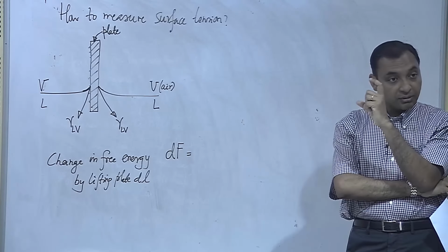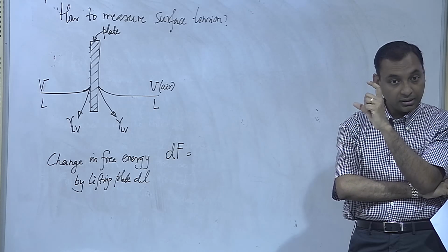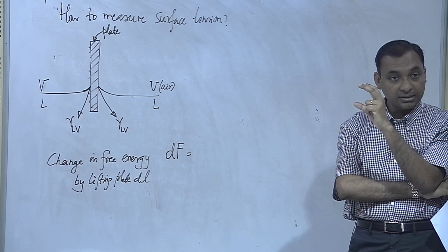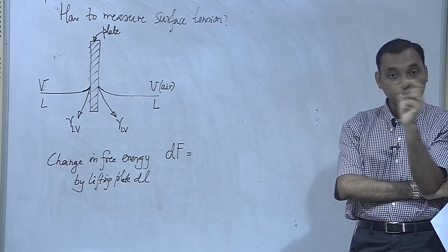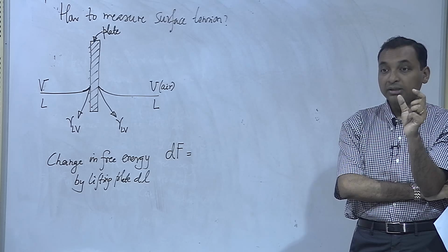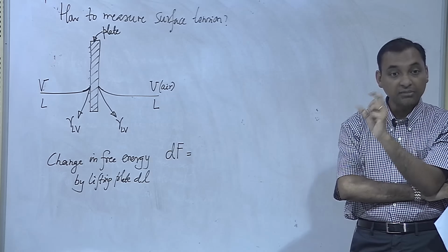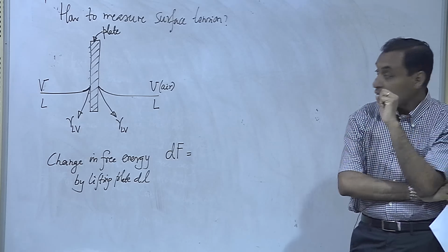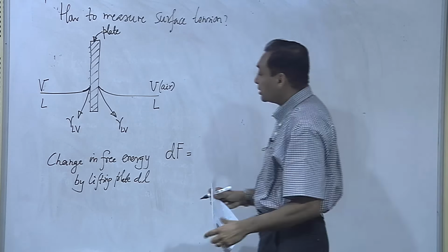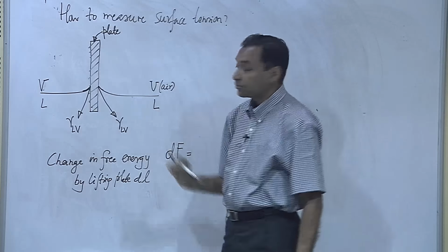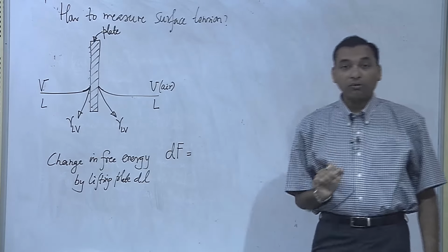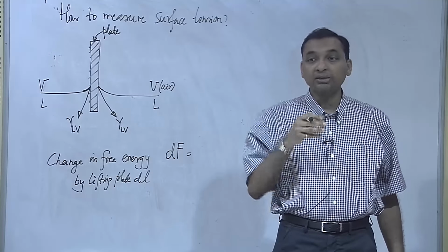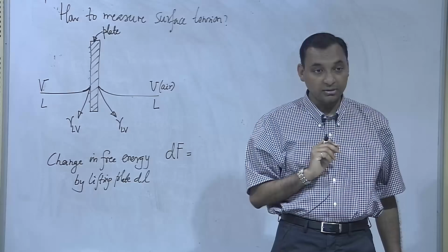So, free energy, remember, it is coming from that U, right. So, U, our cohesion energy, can be measured in terms of the surface tension times the area, correct, the exposed area. So, if I withdraw this plate, what happens to my change in free energy? So, some energy gets created, some energy gets lost, right.